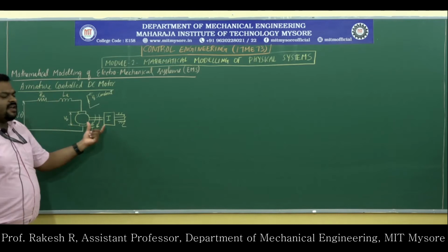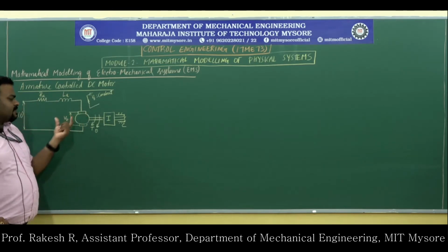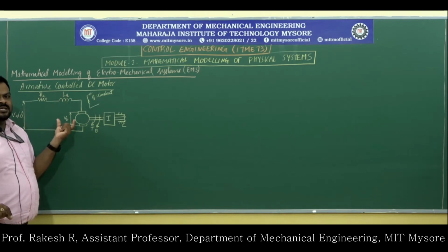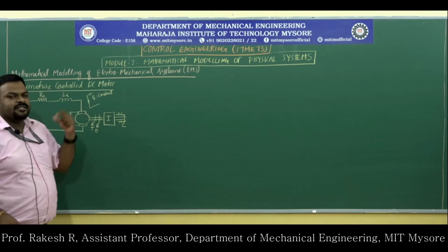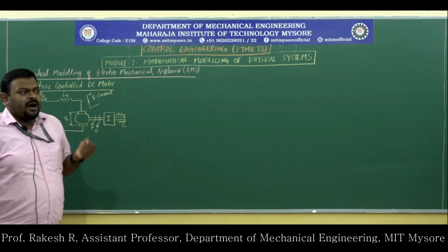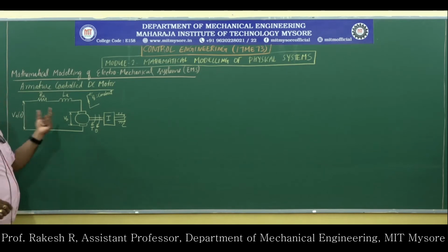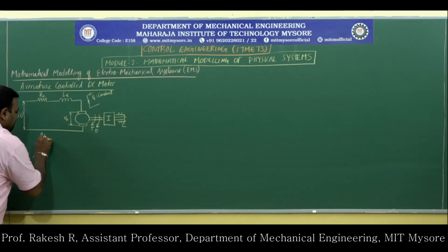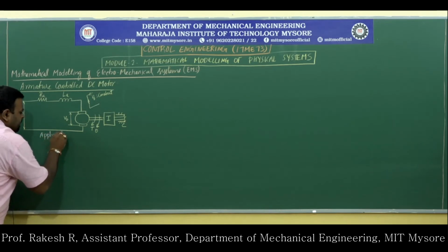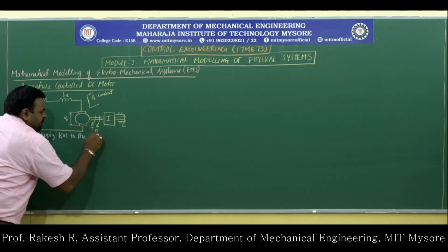What I will basically do is mathematically model the armature controlled DC motor with respect to the supply voltage as well as the rotation. Let us see how to model this. Since it is an electrical network, I will first solve the electrical network by applying Kirchhoff's voltage law to the circuit.